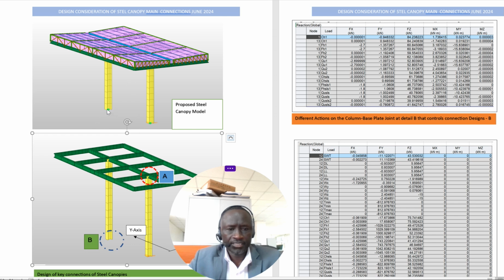The fixity at the base plate area, for these sensitive canopies, it's also not bad if you encase it after bolting and doing all the connection, to avoid the corrosion and durability challenges. Try to control water movement around here, get proper drainage to keep it dry all the time so that the connections are not affected by corrosion.